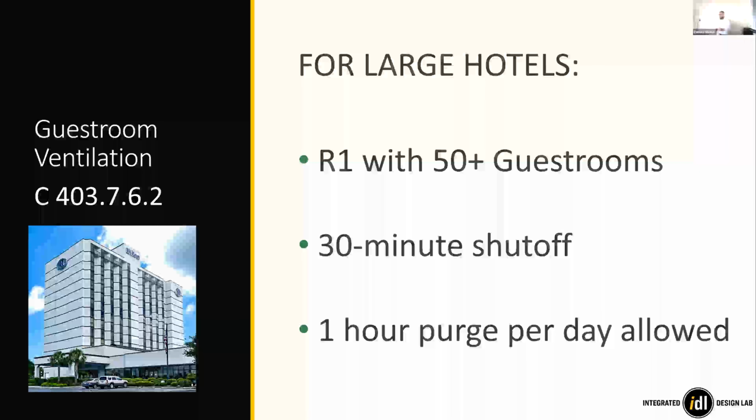people arrive. It doesn't say exactly what kind of controls are required in order to do this, like how you're measuring this. This could be an occupancy sensor within the room that's detecting motion, or your key card systems. Hotels in Europe, you kind of have to put your key into the slot once you go into the room so that it shows that the room is being occupied, and then you have to take it out when you leave. Or even if your hotel has software showing which rooms are booked and when, all of that can work. You just have to argue to the code official, here's your design intent.